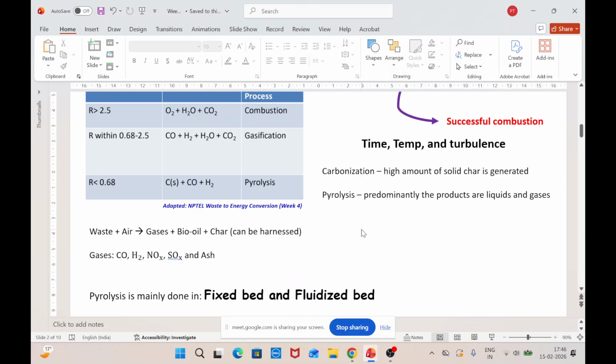As engineers, we should know that if you burn this much, this amount of heat should get generated, and these are the gases that will be produced theoretically using equations. Of course designing is different, but at a preliminary scale we need to be able to judge how much heat will be generated, what type of gases will be produced, and in what distribution these gases will be generated within the system. However, if the feedstock is not uniform, this estimation is going to be extremely difficult.